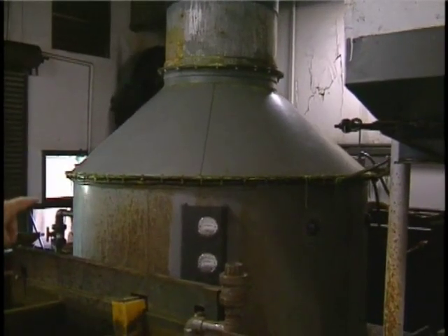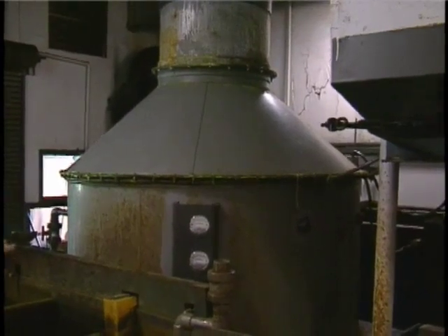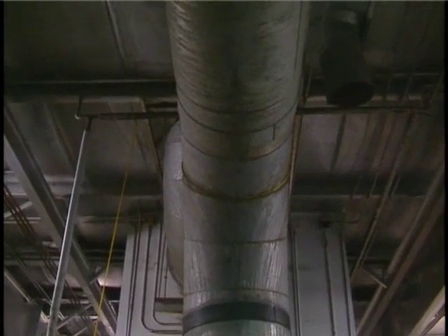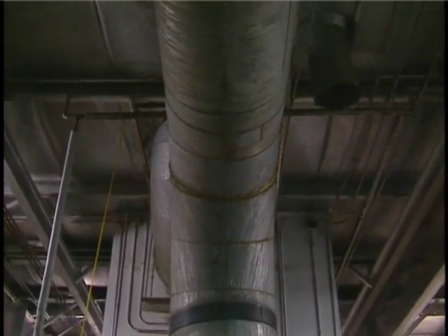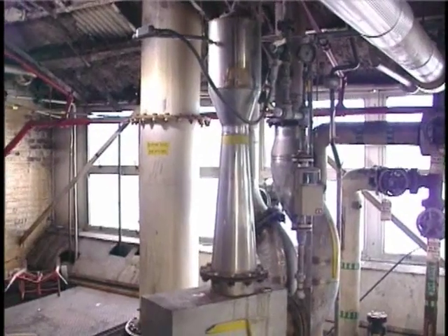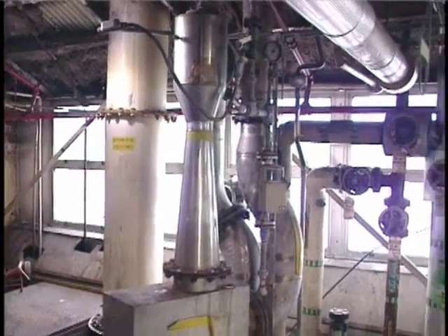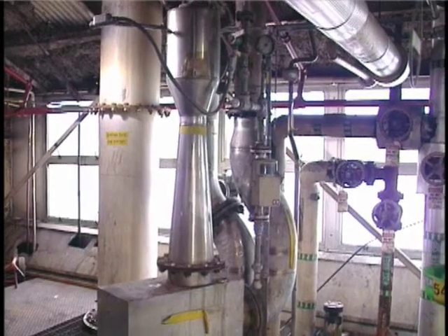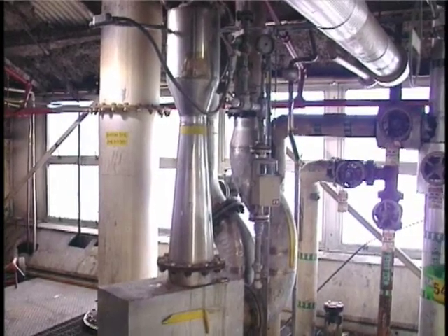Changes in scrubber pressure drop can occur for several reasons. Increased pressure drop across a packed bed or tray scrubber may indicate plugging of the bed or trays. Increased pressure drop on a Venturi scrubber may be caused by increased liquid flow rate or by adjusting a variable throat damper to a more closed position.